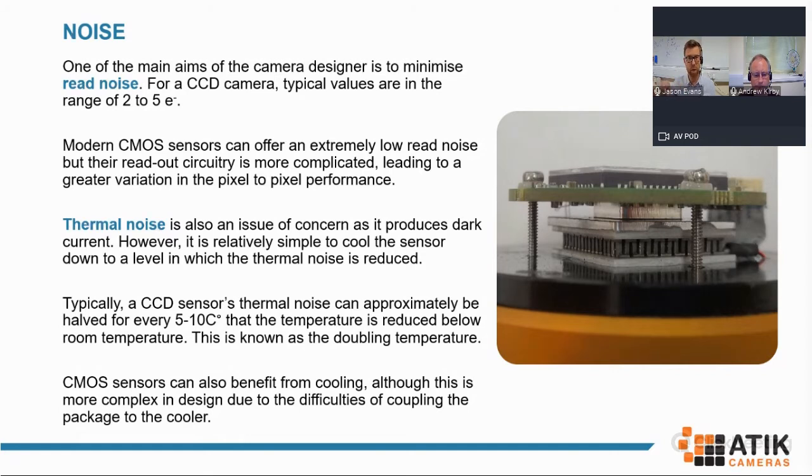If you view it as a sort of a curve, it's quite a rapid improvement down to about -10, at which point that improvement gets less and less. So a lot of people you'll find, and a lot of camera manufacturers, ourselves included, don't seek out to get that cooling much below sort of -10 as a real world figure. Because the benefits just aren't worth the additional cost and investment in trying to get that cooling further down.